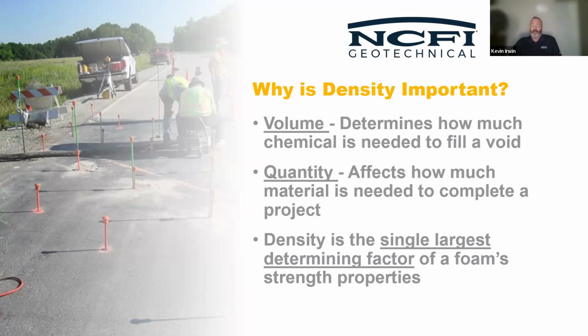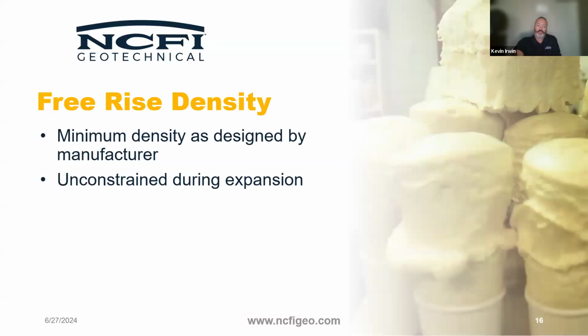Not just the volume to fill, but the quantity, density is going to be directly related to that. And of course, it's the single largest determining factor in a foam's strength properties. And the reason we talk about density is because in the lab, as a manufacturer, we test free rise density of all of our poly systems.